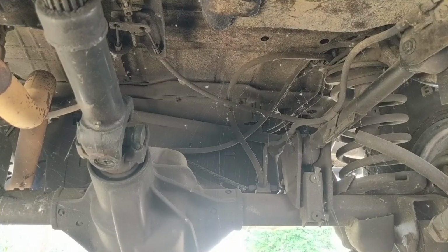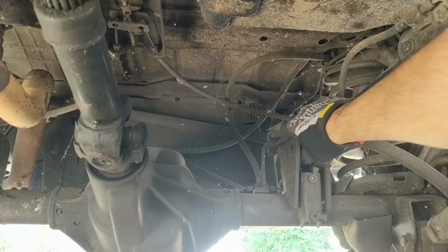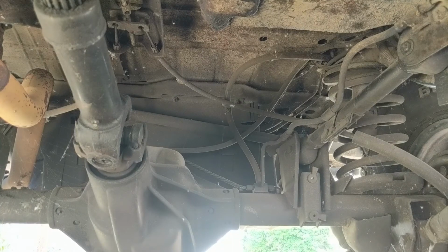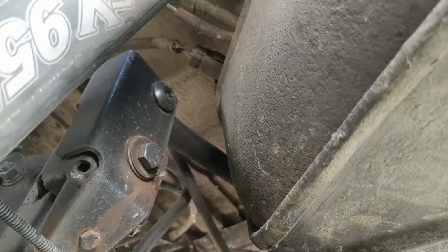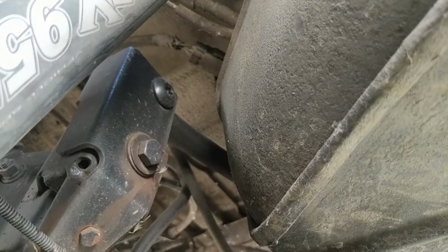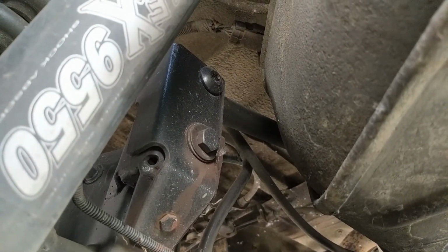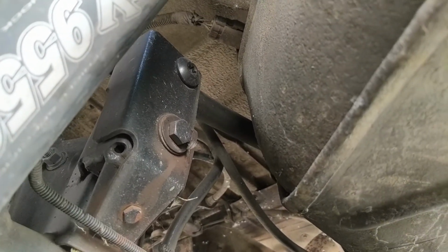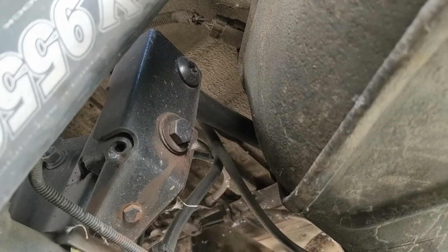It may not be easy to see in this example, but there's a bracket on the back of the axle, and this rod here is our track bar, and that's keeping the rear axle centered with the chassis. Due to the space constraints in here, it's hard to get a good view with the fuel tank in the way. But this is looking at the rear side of the axle on the bracket, and since this Jeep has a suspension lift on it, there's an extension bracket for the track bar to limit how much that arc travel affects the movement of the axle.